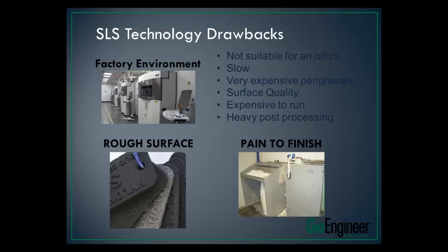In order to maintain this machine, to do anything inside of the build chamber, change out things, you have to wait for it to cool down. The cooling down cycle is equal to the build time. So if you run this thing for 30 hours, you have to let it cool down for 30 hours. This is something that I was told that I didn't really believe, but it's a long time to wait for a machine to finish.